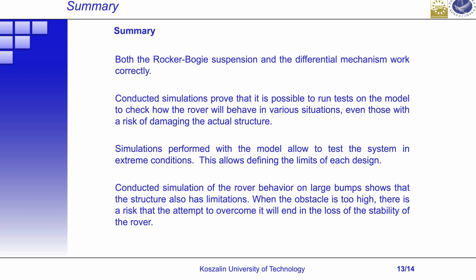Simulations performed with the model allowed testing this system in extreme conditions. This allows defining the limits of each design. As a result, it serves to improve and enhance it. The conducted simulation of the rover behavior on large bumps shows that the structure also has limitations. When the obstacle is too high, there is a risk that the attempt to overcome it will end in the loss of the stability of the rover.